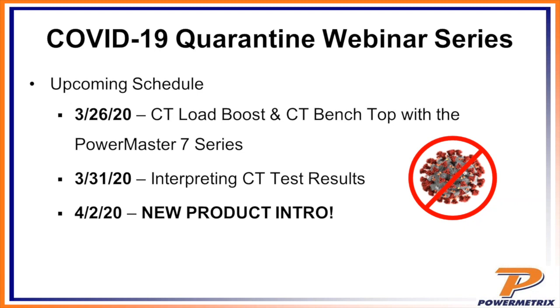That gives you the ability, let's say you can't go out and pull the site CT down, to actually test a CT there in the shop just by using the 7 series load box. And if you're out in the field and you have no load at all, you can actually put a load on the CT to get a good CT test out of it. And then the following Tuesday, we're going to be going over the CT results. We get a lot of questions on that. I think it's going to be a great session. And then don't forget, on the 2nd, we're doing the new product intro.